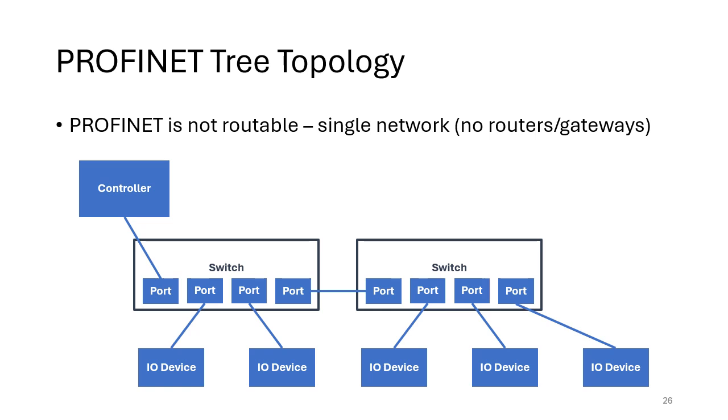Latency would be an issue. Again, if you think about that early switch on the left, that's handling more data than the switch on the right. So potentially there could be issues there, but normally those switches are operating down at the microsecond level, where your network of PROFINET is operating at the millisecond level. So we're orders of magnitude different.